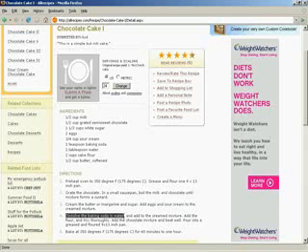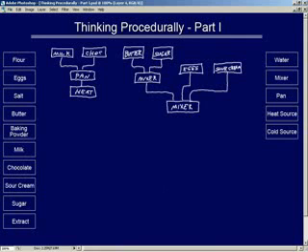All right, so now let's move on to step number 4 in our procedure. Dissolve the baking soda in water. Well, that sounds to me like we're doing something off in a whole other world again. So before we go any further, let's take care of that. Jumping back over here real quick, that means we're going to have some baking soda. So how about I just say baking soda. It's BS, and it was pulled from over here, and we just set the type parameter to baking soda. So we take that, and here we are with water. We've got that node available. So we grab these two guys.